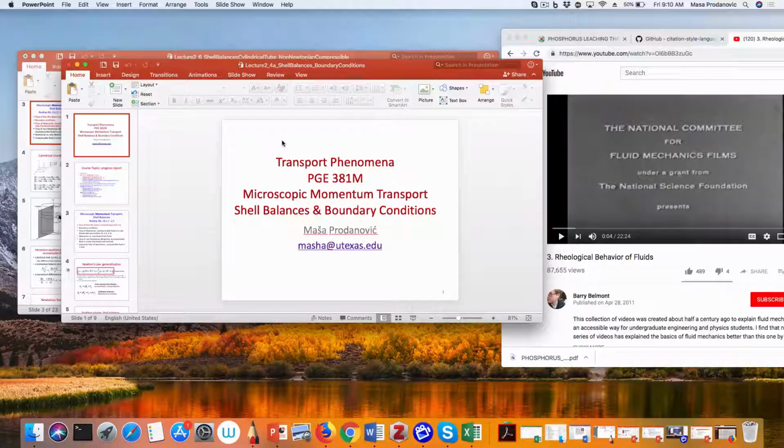So it's providing us with the general form. But we looked at our tube and said, hey, this is a tube, I have R is 0, I can't have shear stresses blow up. So, not in laminar flow anyway. So basically that constant next to 1 over R has to be 0. So math can't tell me that. I have to look at the situation I have and actually apply the actual boundary condition.